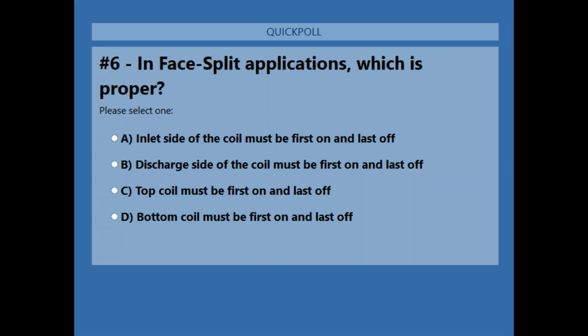Doug, Juma asks, if hot gas bypass is the old method of capacity control, what is the new method? Well, the new method of capacity control, from a big picture, is digital scroll compressors, multiple compressors in the same circuit.